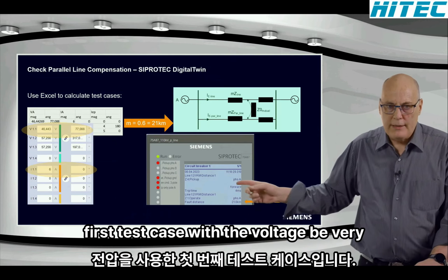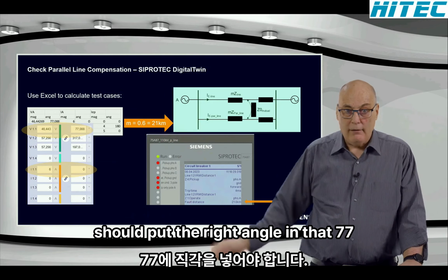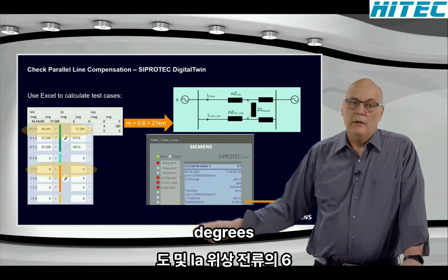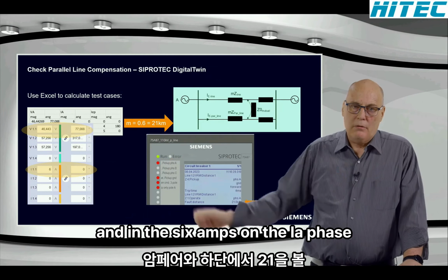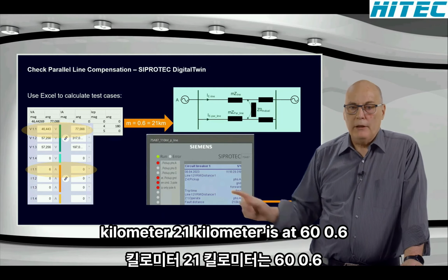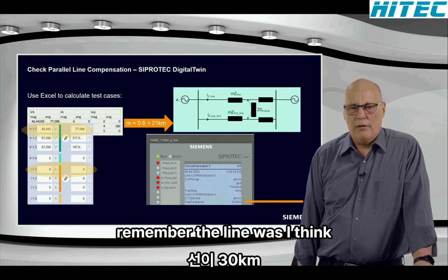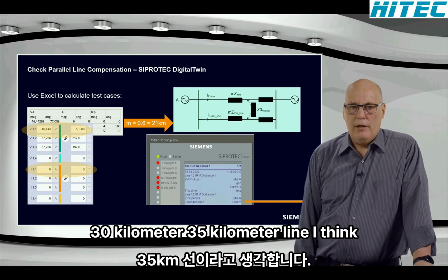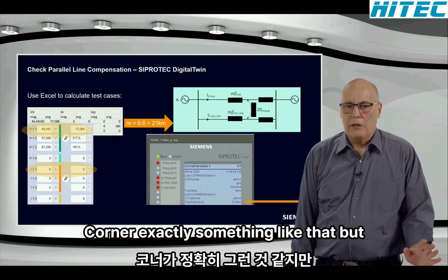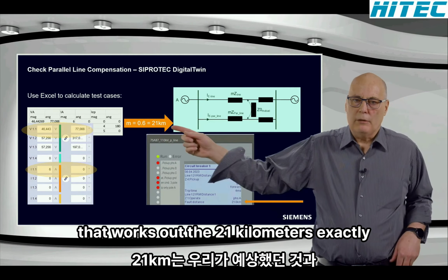You can see that's my first test case with the voltage. Be very sure to put the right angle in, that 77 degrees, and then the 6 amps on the IA phase current. And at the bottom, you see 21 kilometer. 21 kilometer is that 0.6. Remember, the line was, I think, a 35 kilometer line, I can't remember exactly, something like that. But that works out. The 21 kilometers is exactly what we expected.